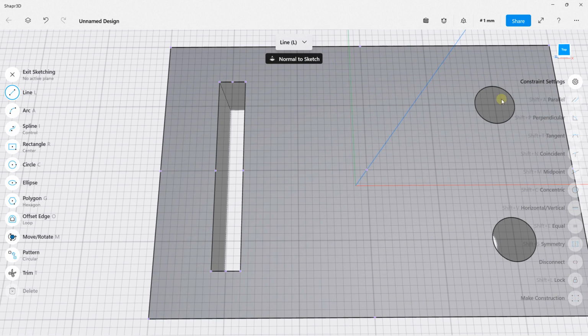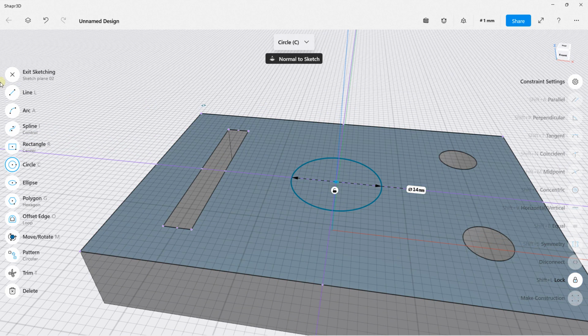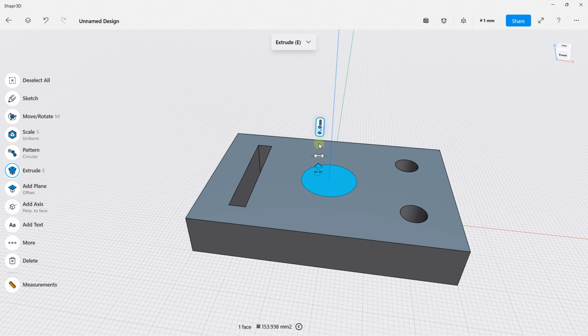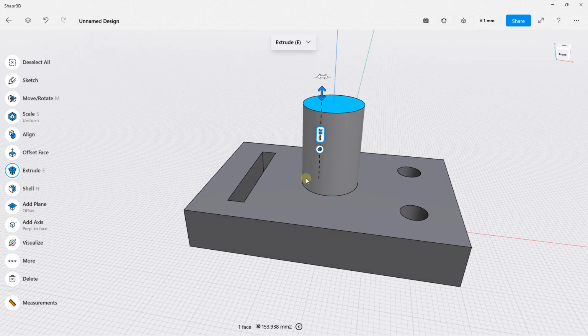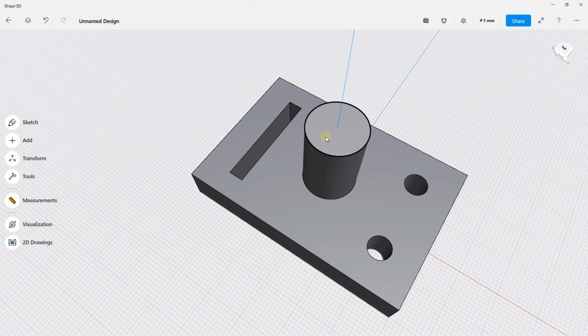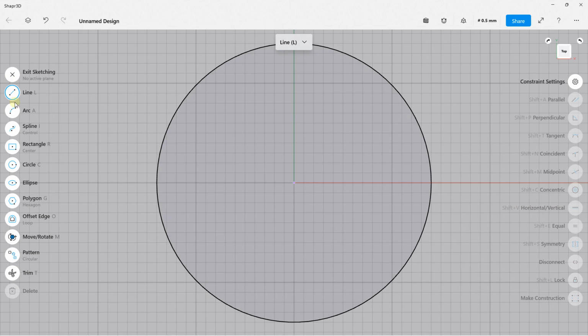And if I select my top view, let's create another element. It can be a big circle in the middle. I can snap, let's apply 14 millimeter. And I can finish my sketch, and I can click here and create another extrusion just like that. For example, with 20 millimeter. If I want to create a hole in the middle, I can click on this face, create a sketch, and automatically you arrive perfectly on the view. The ergonomic is really convenient.